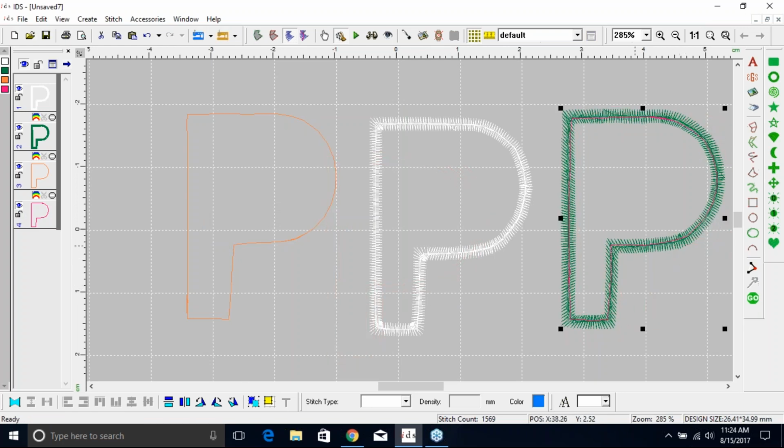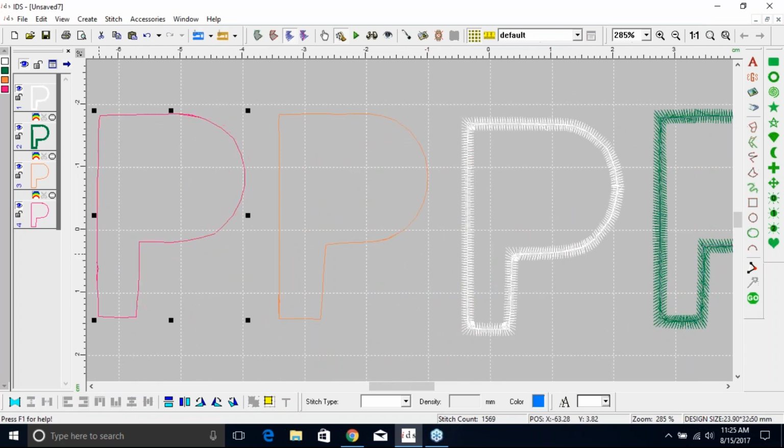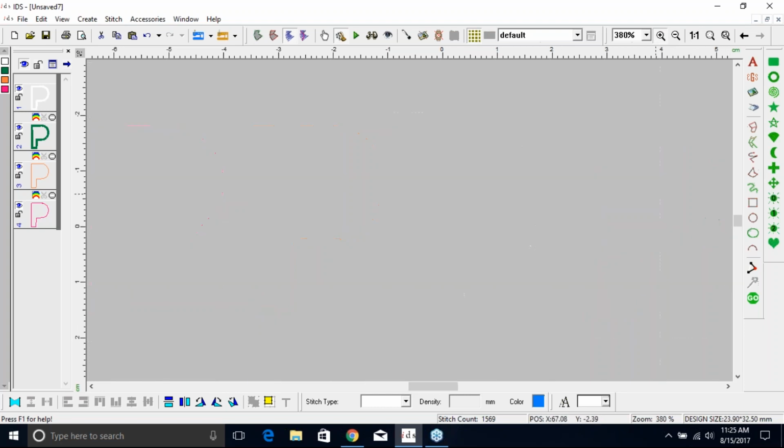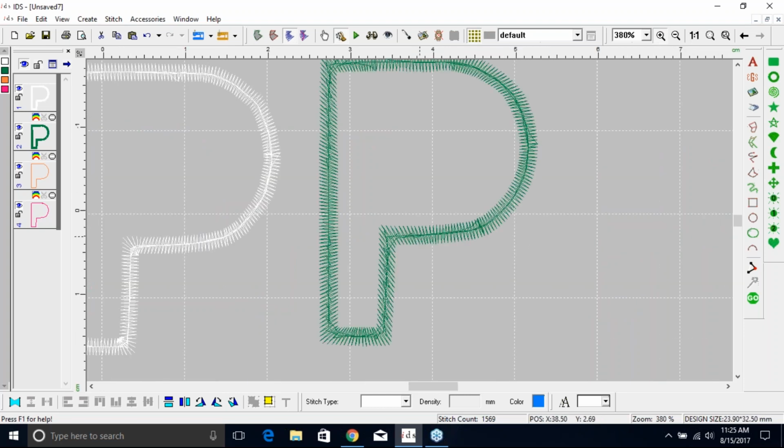And again, they're grouped. So we'll go to Group, Ungroup down here. So it actually did a better job if you do create outline. So creating a negative offset, put it inside, because I took the interior area, created a negative offset so it went inside the stitching, and I did it at negative 0.5.